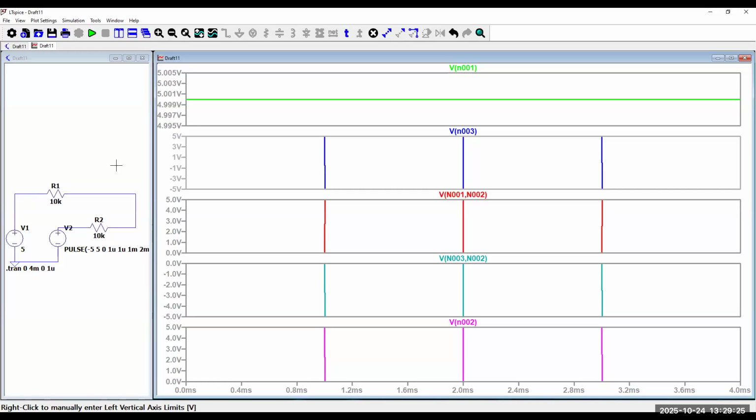Hint is the voltage. Absolutely. That's the answer. We flip the voltage source, or instead of applying positive 5 volts, we apply negative 5 volts. Negative 5 volts means we are simply flipping that voltage source. So I'll show it to you here. I can cut it out and do it, or an easier way is to simply change that 5 to -5. If I change this 5 to -5, it's now negative voltage being applied, and keep an eye out for the last waveform, the one in purple.